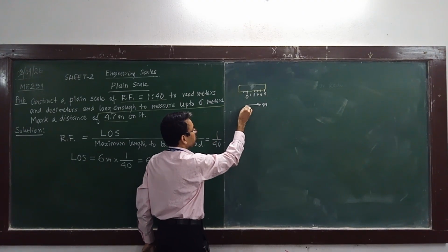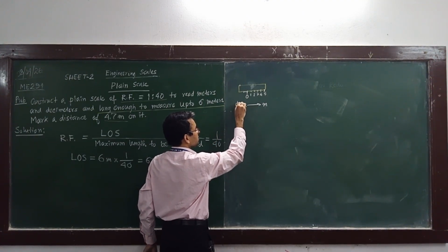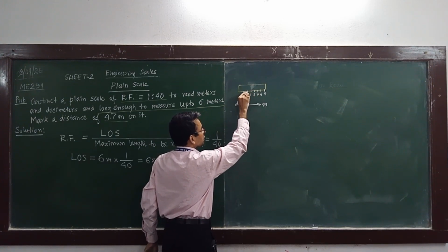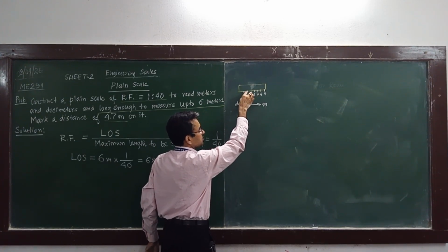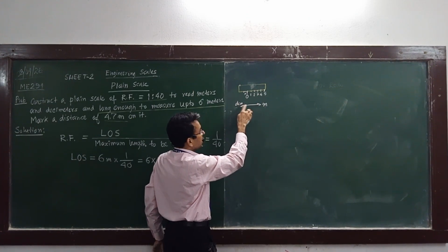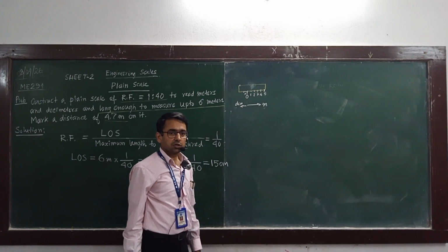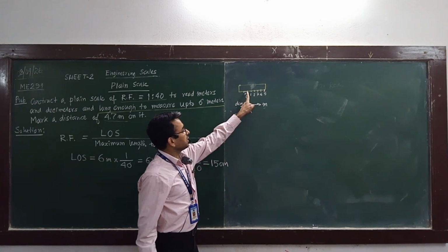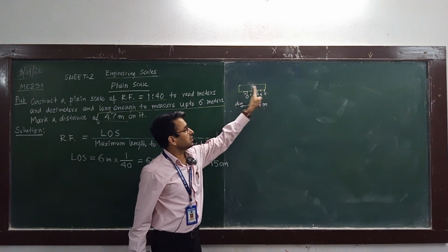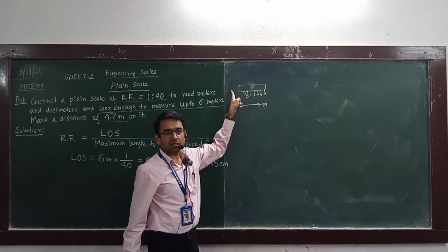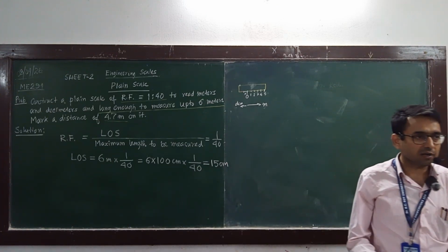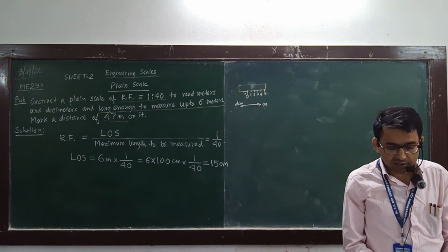Now this side it will be decimeter, say DCM for example. Now here 0, then 1, then 2. When I read 1, that means 1 decimeter, not 1 meter. Because in this direction it is decimeter unit, and in this direction it is meter unit. So two consecutive units having the same starting point, one 0 for this direction, another 0 for the opposite direction. So that will be the construction of the scale. Okay, is it clear?